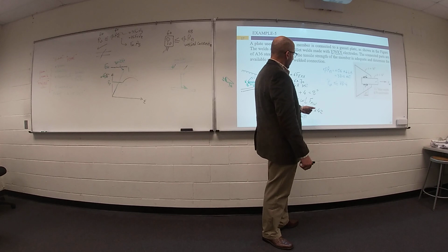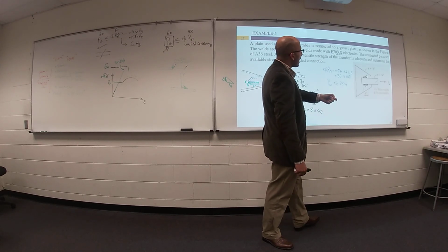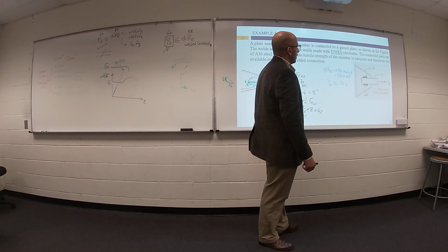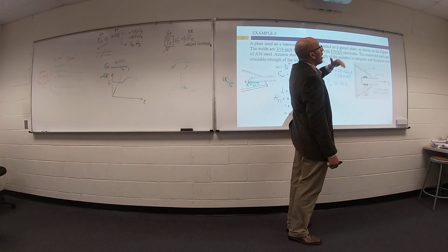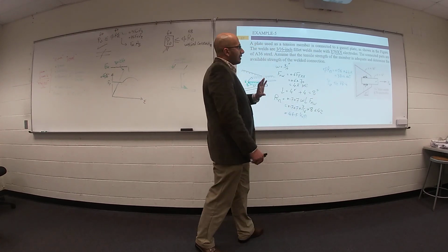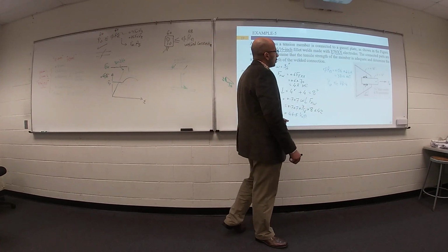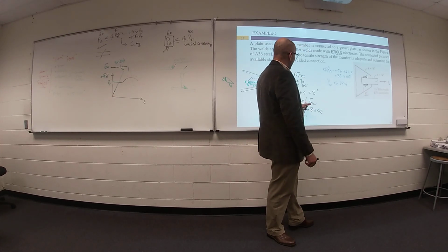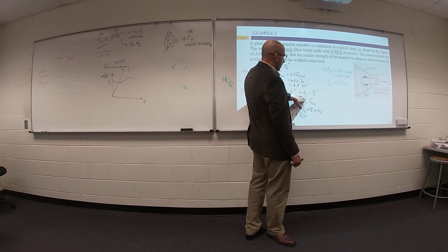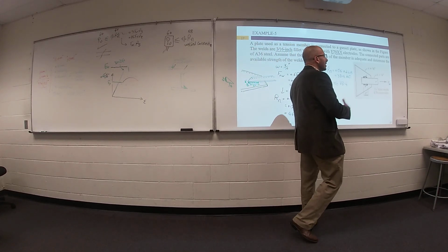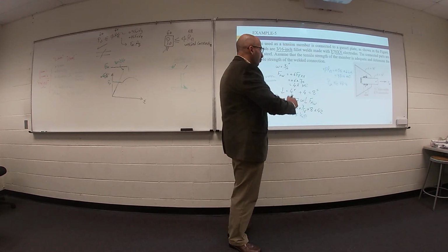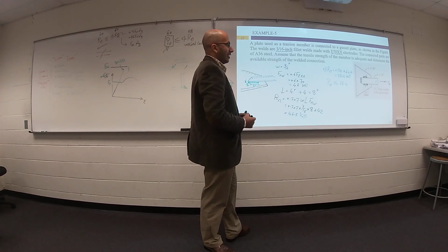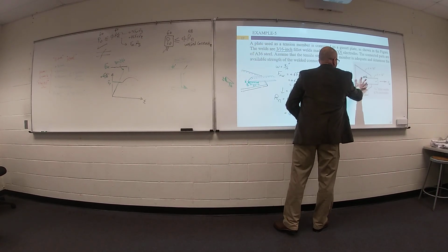The third option, change the type of your used electrode. You used E70XX, maybe 80, maybe 90, maybe 120. But this is the last option. But I think the first option you can change. First one, change the length. If the length is not enough, okay, go ahead and change the system. You can add transverse welding. Then we will go to another calculation, which will be the second example.